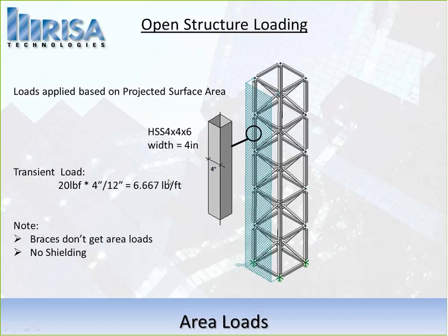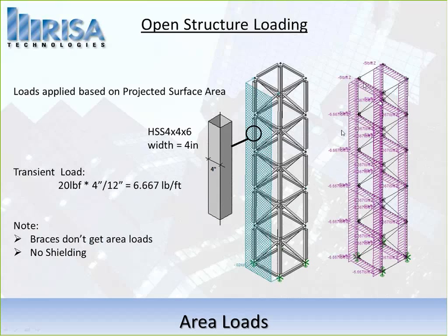So as I blow the wind through there, I'm going to see that the front face column in this scenario gets wind. The back column is also going to get wind. The beams are going to get wind. The braces are not going to get wind. And we can see that here in a second.